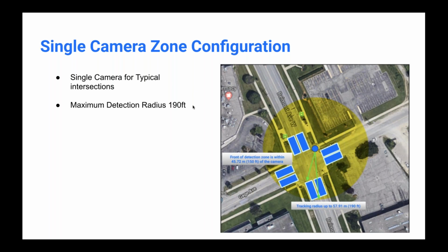So when it comes to actually planning how to integrate the detection into the intersection, you do have to plan for the camera's location. The camera can be mounted on a number of different surfaces. I think I said a little bit earlier, you could mount it on a mast arm, a luminaire, a signal pole.